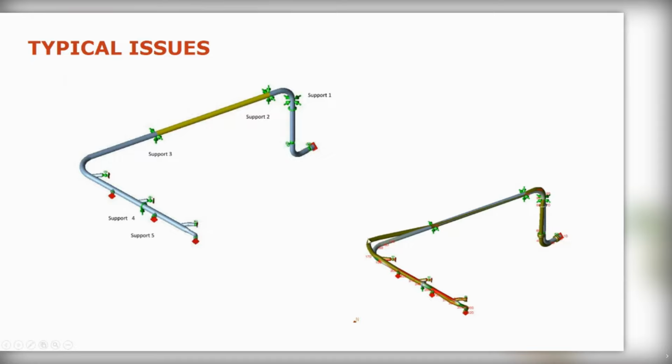The problem is, as you can see, this is again an over-exaggerated schematic from the pipe stress analysis software. This elbow is being pushed right up and out, and this is pulling on those nozzles, but those nozzles are really anchored into those big cast bits of equipment. Therefore, the pipe goes under a lot of stress and it breaks at its weakest point, obviously. So that's a problem here. There's not a lot you can do with moving supports around because the pipe itself is already restricted by the nozzles.